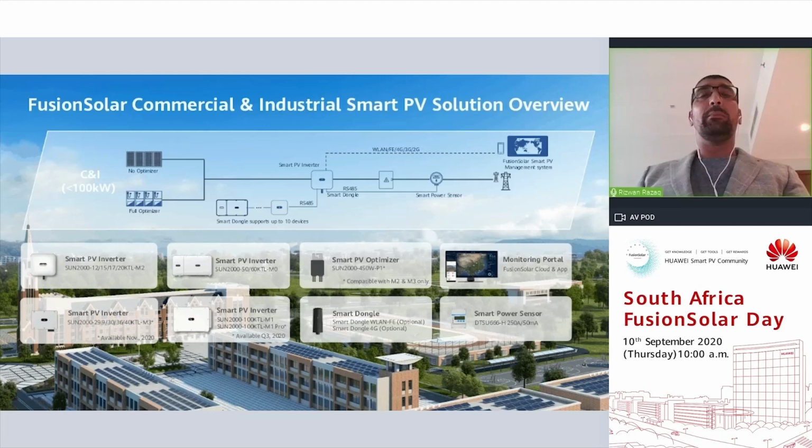Now, as for the C&I applicable projects, you may be more opted to have a zero export functionality or limiting the export. So Huawei is also providing a smart power sensor that can be used for the functionality to communicate with the inverters or data loggers.